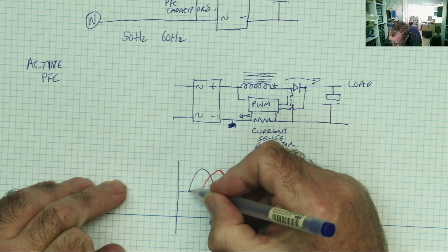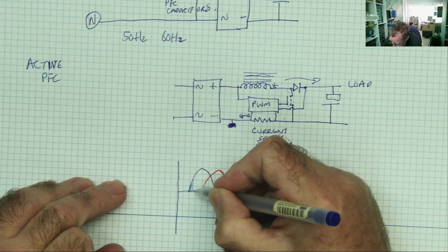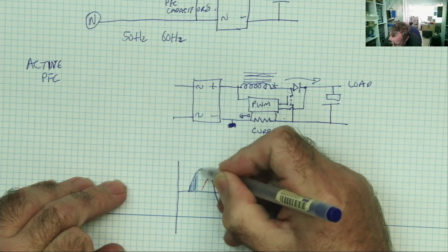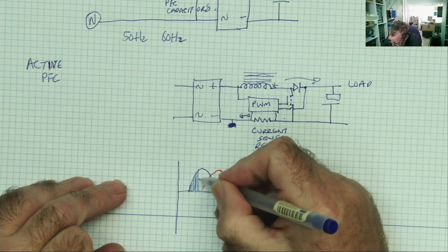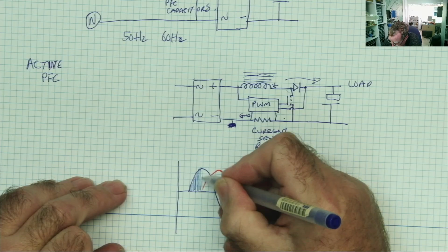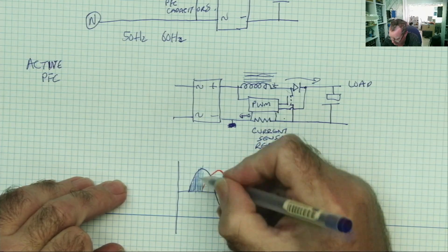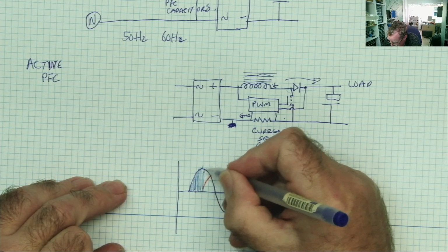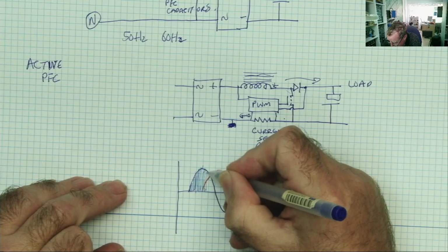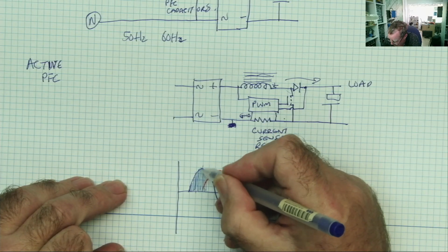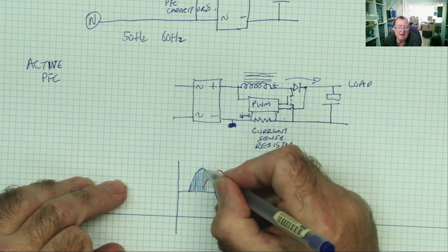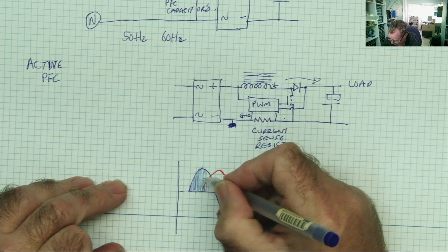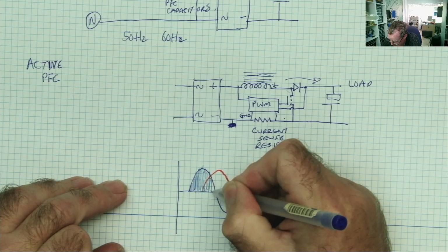So it's switching on and off all the time. Yeah? On, off, on, off, on, off. And each time it switches on, it draws current. So it's switching on and off so rapidly that although we still technically have this 90-degree shift, within the time this is on and off, when we're near the peak of the waveform, we still approximately have the same voltage and the same current at the same time. Okay, you see that?